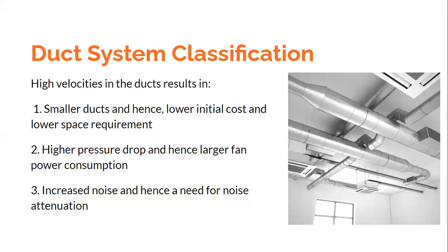If that leads to higher pressure drop, that leads to higher consumption of electricity in the fans. That is a disadvantage. The second disadvantage, as I said, has to do with the noise. If you go for higher velocities, imagine that the air is flowing with higher velocities, it would make more noise. Yes, one can imagine this. If you experience, for example, the winds, what are winds? Winds are air flowing with higher velocities, and we know that that creates noise.